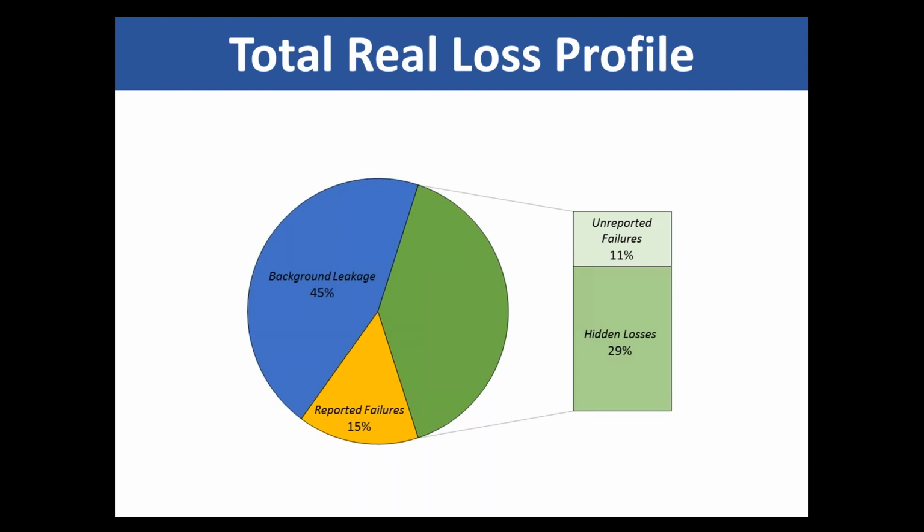And so we had the data from those surveys for that year, how much they found and how much leakage they recovered by doing that. Now, when we were done with this analysis and I looked at it, I said, well, you're surveying 30% of your system, but you're not recovering 30% of the unreported leakage out there. Something doesn't match, right? You would actually think you find more than just the 11% because they're covering 30% of their system.